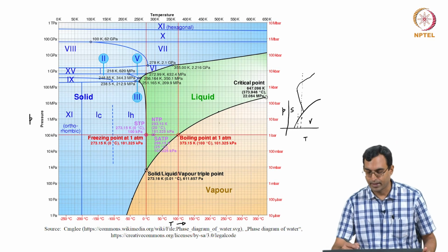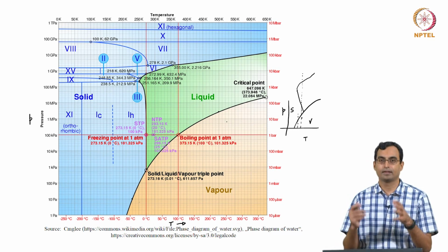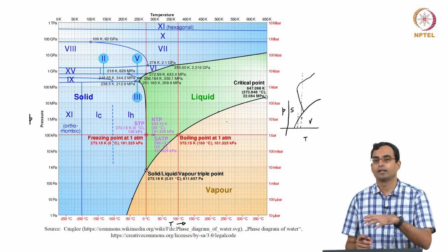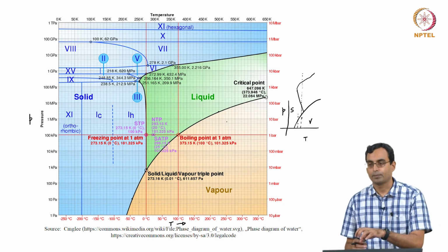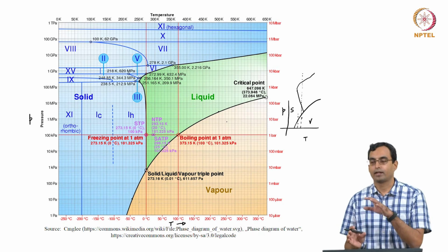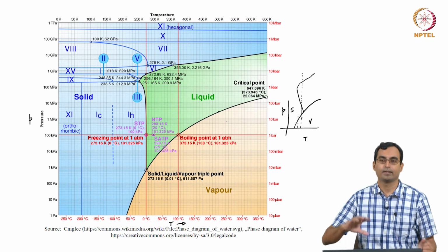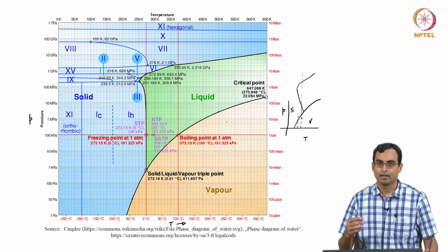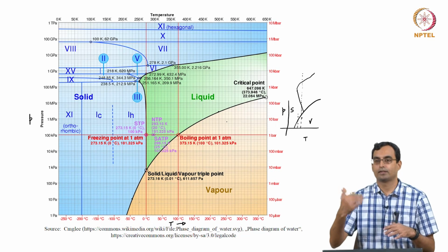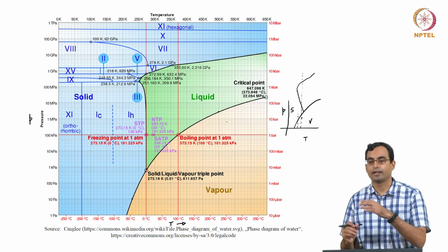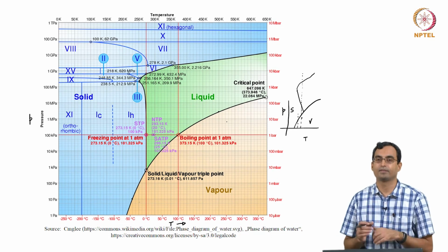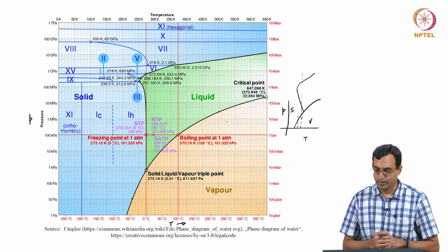The same thing happens when I have, for example, liquid and vapor. So, in this piston cylinder arrangement, if I have a frictionless piston cylinder arrangement, and I fix the temperature, and I have some amount of water in it, some amount of vapor in it, if I look at it after a while, the amount of water and the amount of vapor will still be the same, the fraction will be the same, because they are in equilibrium. The water is neither evaporating beyond the net rate, nor is the steam condensing. So, steam is condensing at the same rate at which water is evaporating. It is in dynamic equilibrium, but the masses remain fixed. So, that is essentially what we mean by equilibrium.